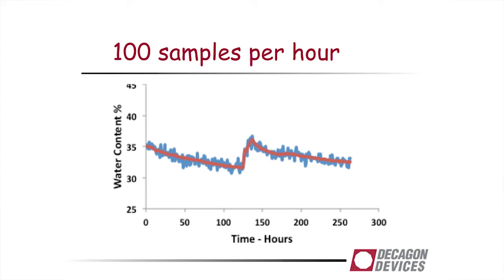A ridiculous thought, but again, there's still some variation in it. It still doesn't look anywhere near as good as the in situ sample. When we're just looking for the changes in water content, the water storage, the water use, in situ measurements make a lot more sense than soil moisture sampling.